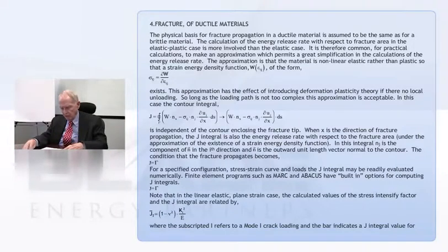So to me, this is a huge jump from the point of view of physics, in that the same condition is being used for the advance of an elastic controlled crack and one that has plastic deformation. If you think about it, in a brittle fracture, almost all the deformation occurs right at the fracture. If you look at some of these pipes that they blow up, I was saying that I gave you some limit loads for pipes. I got involved in a lot of blowing up of pipes, mainly watching and measuring, and you get significant thinning of the wall section at the location of the fracture.